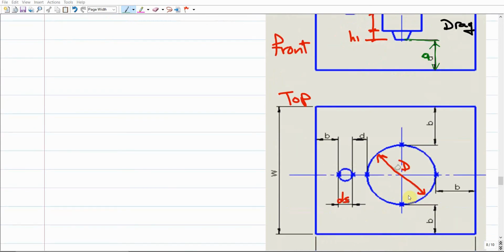From the top view, for example, what is the length of the sand that should be on the side? Because here we are looking at the sides of the sand. How long should the sand column surrounding the casting be? There would be liquid here, so there would be pushing everywhere. To avoid this, the sand should have a suitable size here, because there should be sand everywhere. So this length shouldn't be less than B, and all of these dimensions shouldn't be less than B.